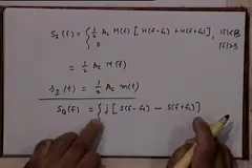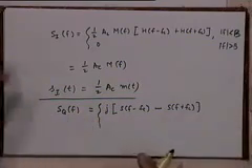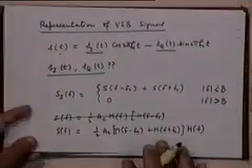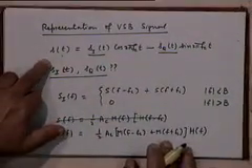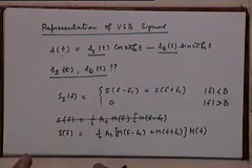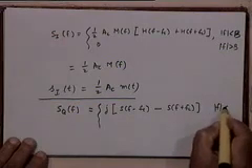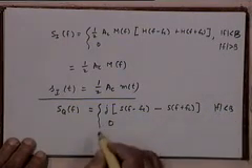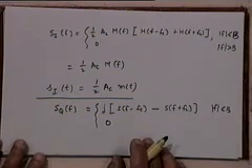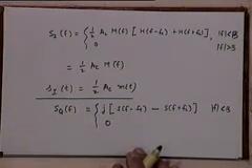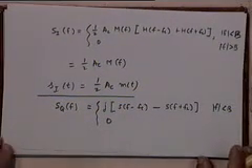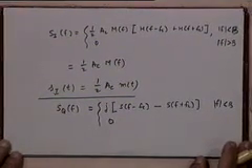Again, as you know, when you multiply s(t) with sin 2π fc t, you will get two terms, one around baseband and the other around 2fc. So we have to low pass filter the result, right? So we are only looking at the portion of this spectrum for |f| < B, because outside this it has to be 0 because of low pass filtering. s_Q(t) is also a low pass signal.